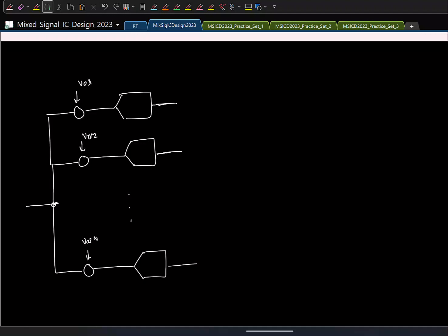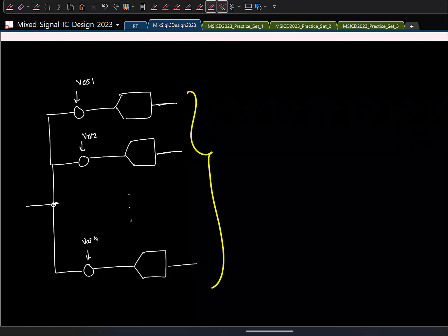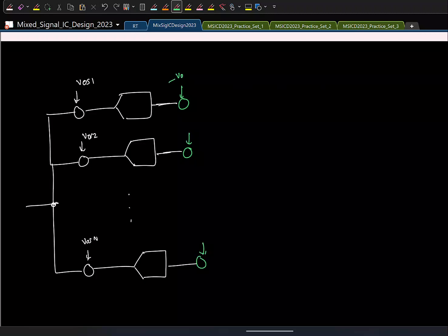Till this point, whenever we had offset in the circuit, what was our approach to correct for the offset? We used to subtract that offset. We somehow get an estimate of that offset and add some quantity in the reverse polarity, right? Now, where can we add this offset in the reverse polarity here? After the ADC. In principle, you can add it in the analog domain too, but adding things in the digital domain is much easier. So in principle, you go and add a small digital number which corresponds to this.